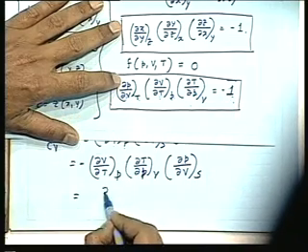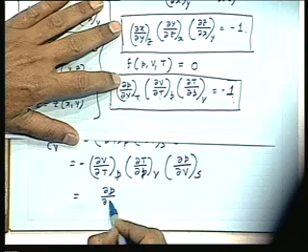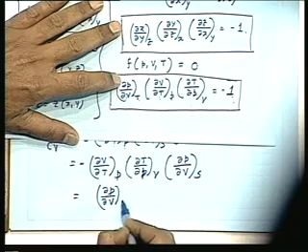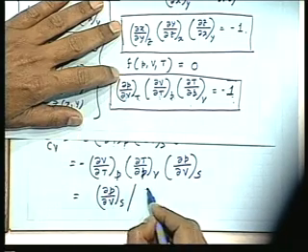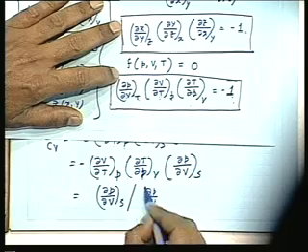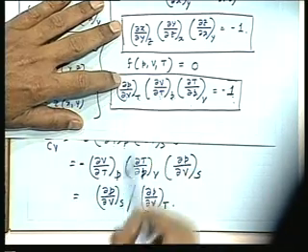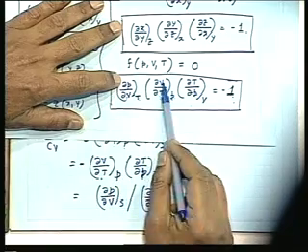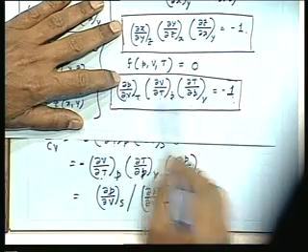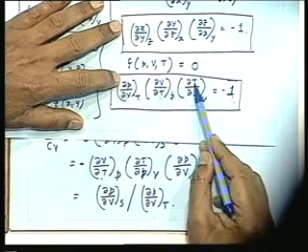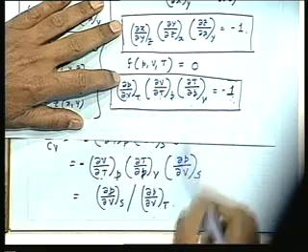That means this becomes del V del P del V S divided by del P del V T. Clear? So this minus sign will go, because this del V del T at P, and del V del T P will be minus 1 by this, so this comes here. So I am replacing del T del P V from this cyclic equation.